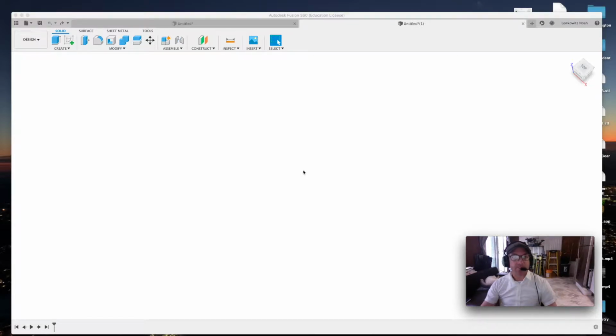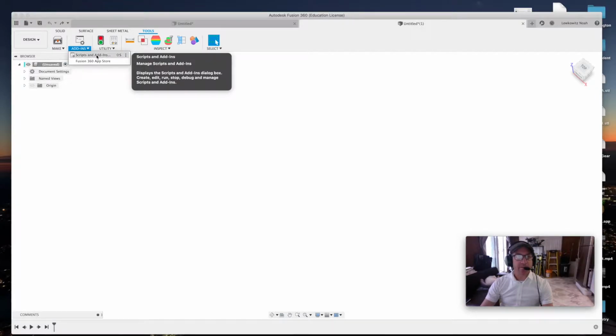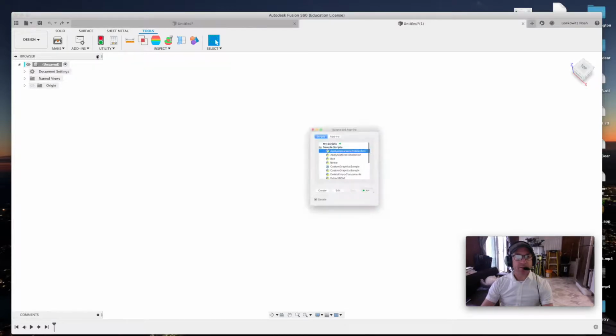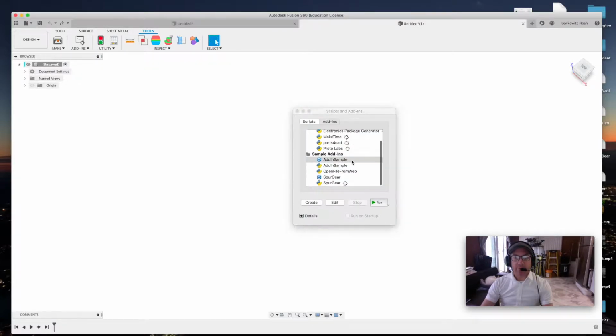So let's get started. The first thing that we're going to do here is come over to the Tools menu up top, click on that, and we're going to use something we probably haven't used much in class or talked about, and that's the scripts and add-ins. Click on that, come over to add-ins up here at the top, and then scroll on down to spur gear.